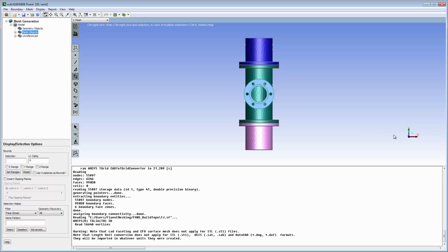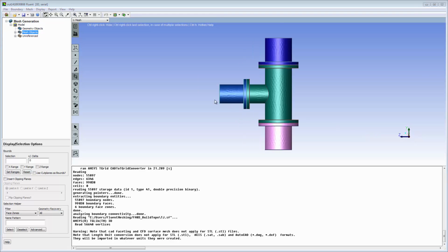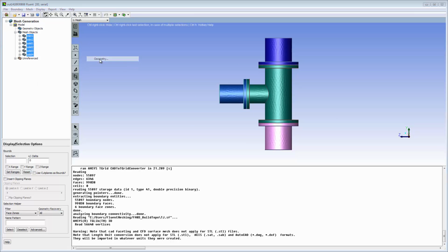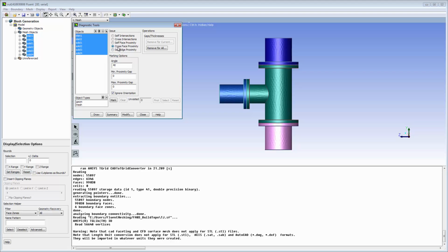The model consists of 4 pipe objects joined as a T-junction. The Diagnostics tool is capable of detecting and repairing common geometry errors. Specify the type of issue and relevant parameters. For example, a gap smaller than 1/20th the minimum face size should connect without explicitly closing the gap.